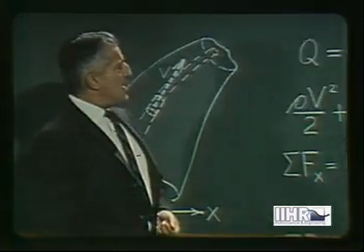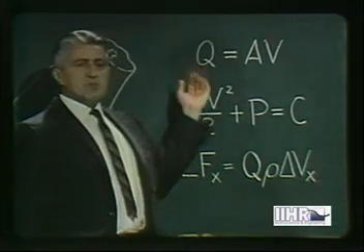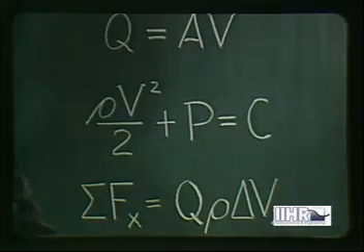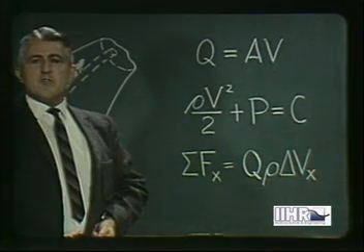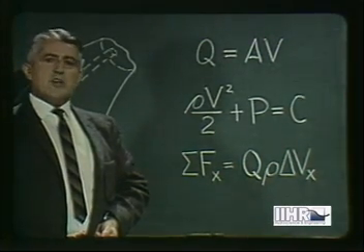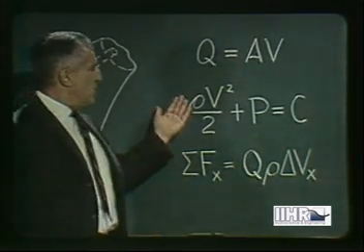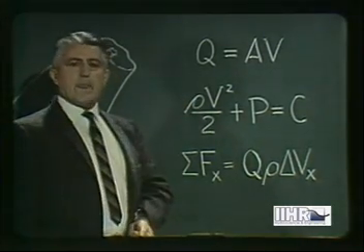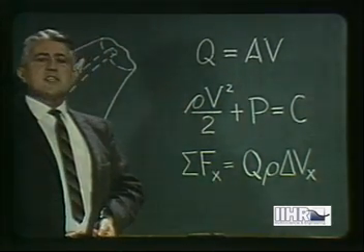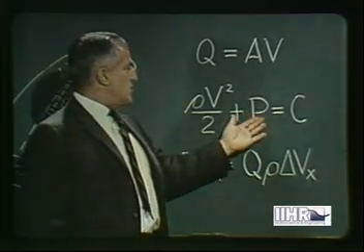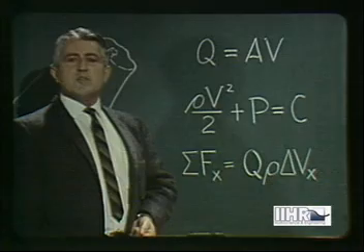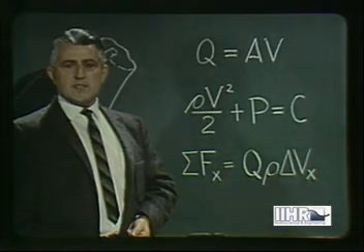The integrated equation of continuity is much the same as before, except that now the velocity represents the average over the entire flow section. The integrated equations of acceleration take either of two forms, depending upon the manner of derivation. One form, the work-energy equation, is very similar to the pressure-velocity relationship used in connection with the flow net, except that now the pressure, as well as the velocity, refers to the entire flow section.